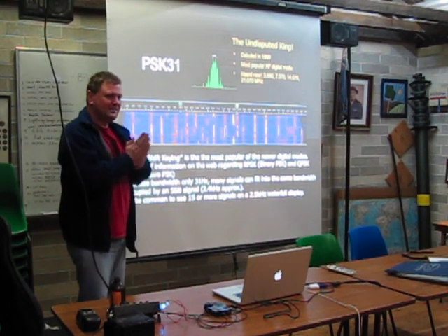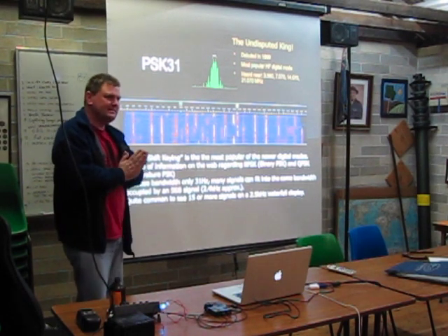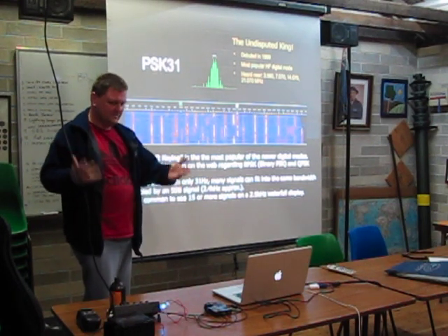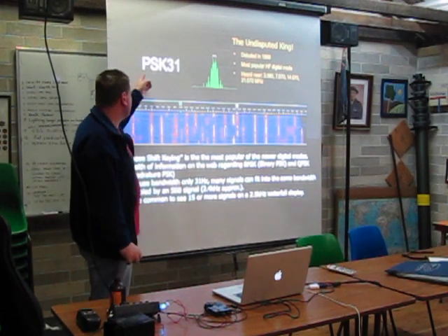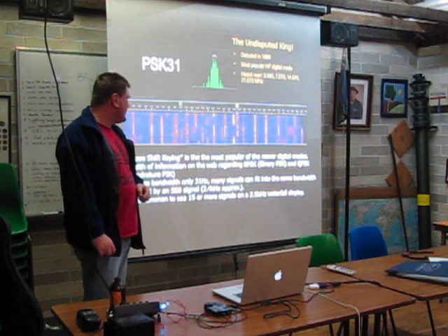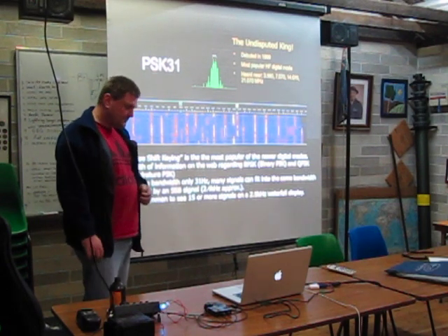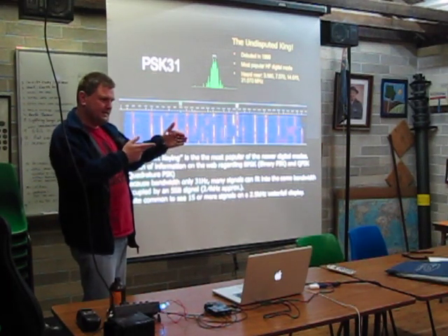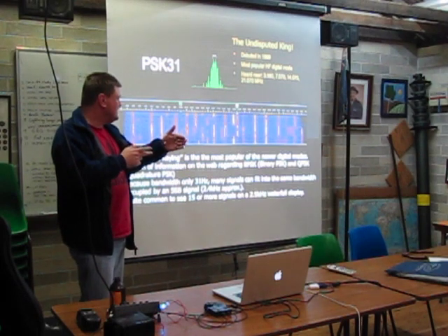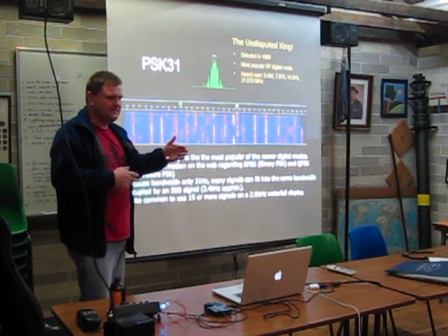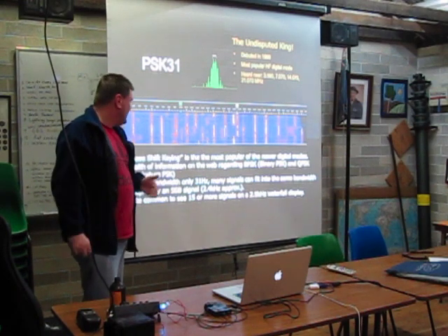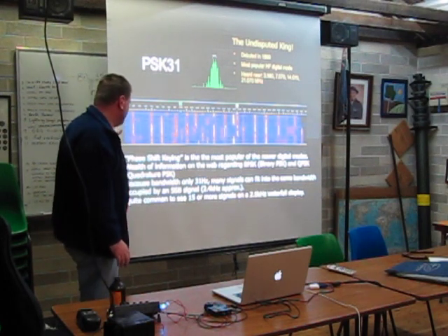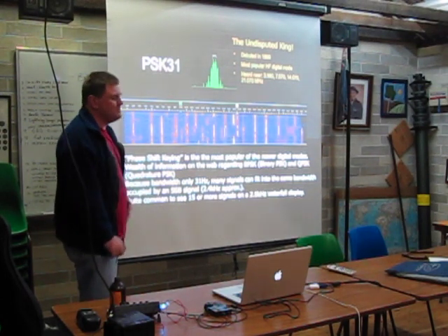Okay, so the first mode people usually start out with, and this is the mode that really made using your computer sound card with your radio really started the whole idea, is PSK31. PSK stands for phase shift keying, so if you transmit a carrier signal and then you swap the phase back and forth, then you can encode binary ones and zeros. So you can encode numbers on it, and then you can use that to transmit information. This is really one of the most popular modes on the band.